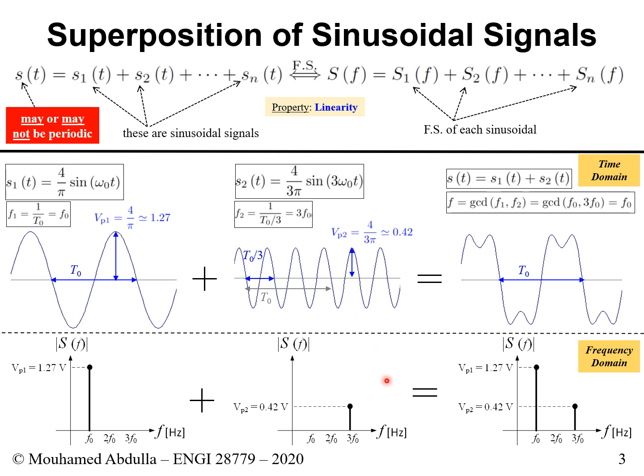Then from the peak voltage, determine the RMS voltage. Once you have the RMS voltage, determine the average power of the signal using Watt's law. Once you have the average power, determine the power in dBs, so in dBW. And then once you have the result in dBW, change it to dBm. So it's just 5 steps, right?